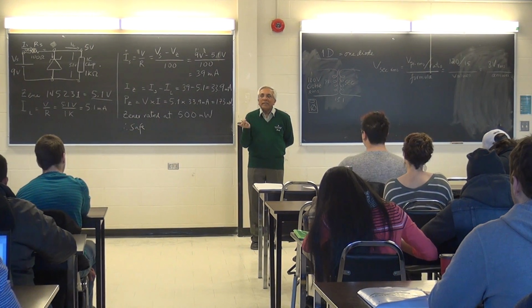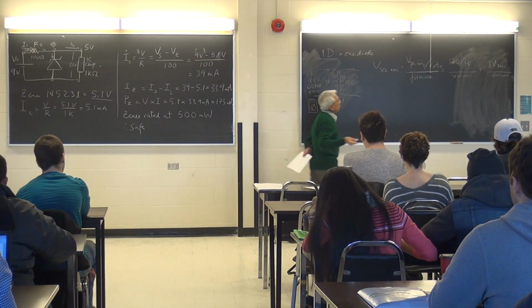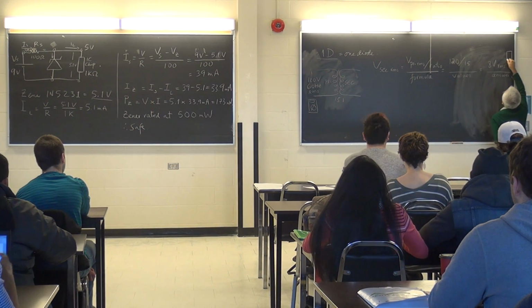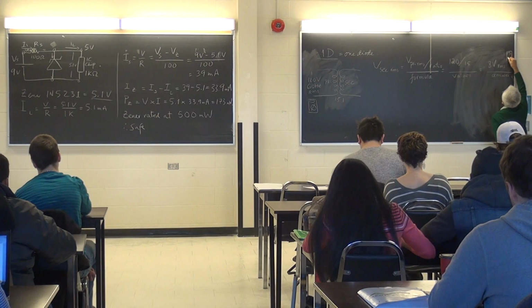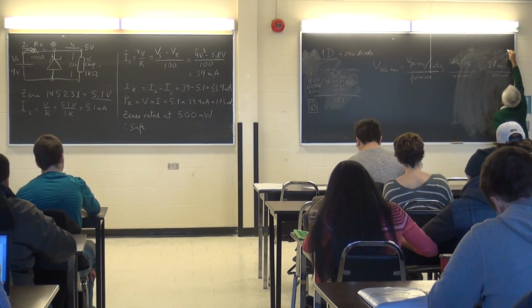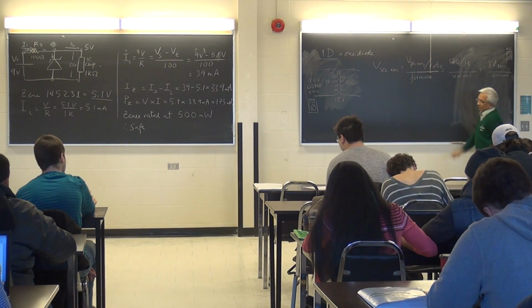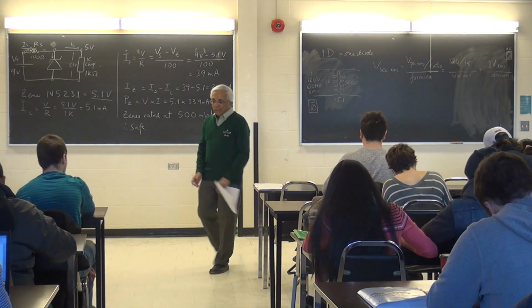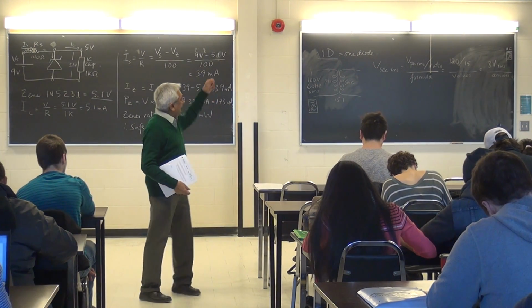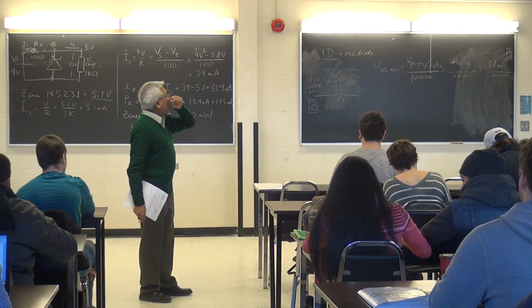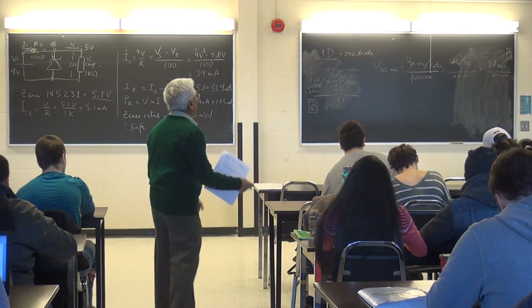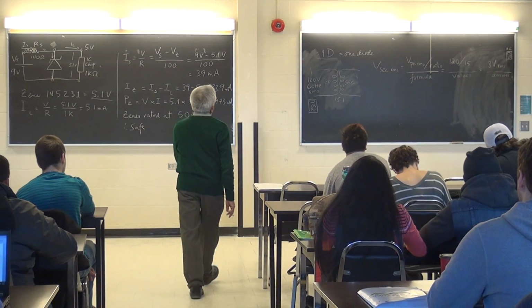A multimeter will read an RMS value. So I'm going to put a little picture of a meter and indicate AC. Okay, so that's what you're going to read on a multimeter. You take a multimeter, you connect it at the secondary, and your turns ratio is 15:1, you'll read 8 volts. Okay.